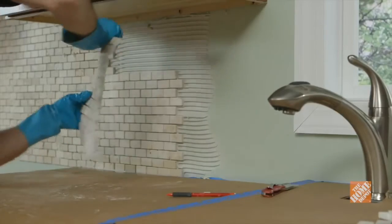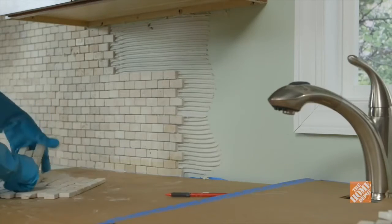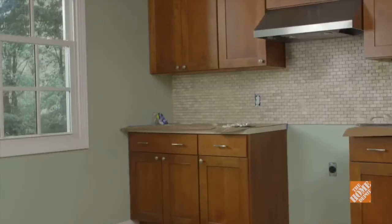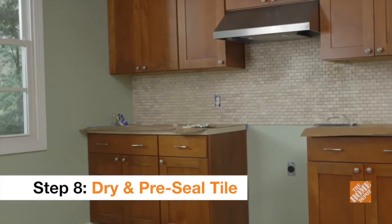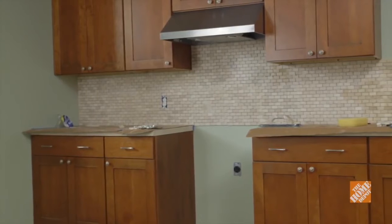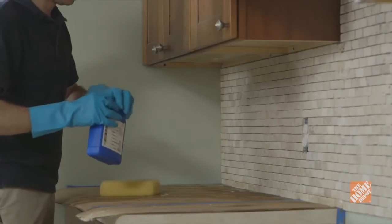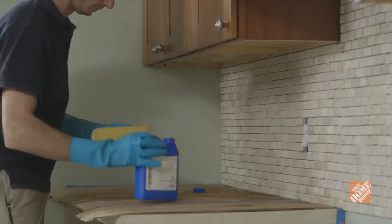If the space between the top row of tiles and cabinetry is greater than an inch, cut your extra tile pieces to fit the space. If not, consider installing a piece of molding to hide the gap. When you fully cover the wall, allow the mortar and tiles to dry completely following the manufacturer's recommendations. This usually occurs within 24 hours, but the timing also depends on the mortar used and the temperature of your home. You also want to use pre-sealer for natural stone at least 3 hours before you apply the grout.